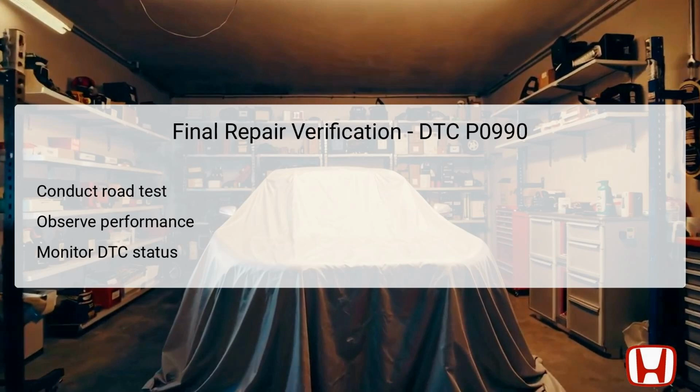This will help confirm that the transmission fluid pressure switch E is now functioning correctly and relaying accurate signals to the powertrain control module, PCM. Additionally, continuously monitor the DTC status to ensure that no new codes reappear, which would indicate persisting problems. An effective road test not only validates repairs, but also provides reassurance to the vehicle owner regarding the reliability of the work conducted. Only after confirming that both performance and diagnostics return to normal should the case be considered complete.